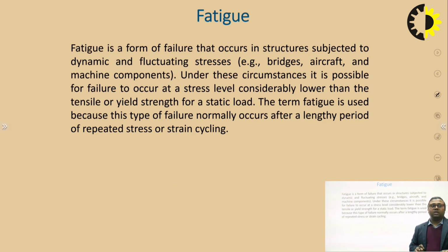The term fatigue is used because this type of failure normally occurs after a lengthy period of repeated stress or strain cycles. Whenever a material is subjected to a particular type of stress for a longer duration of time, it may fail before the yield point. The point at which the material fails below the yield point is known as the endurance limit for that material.